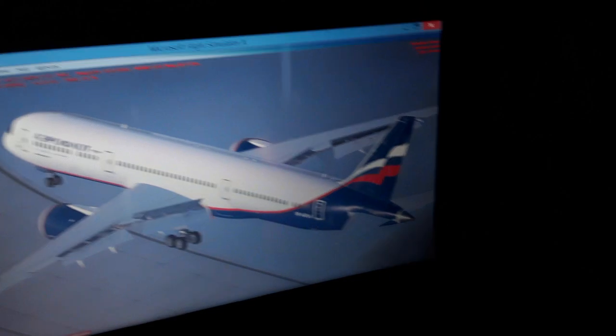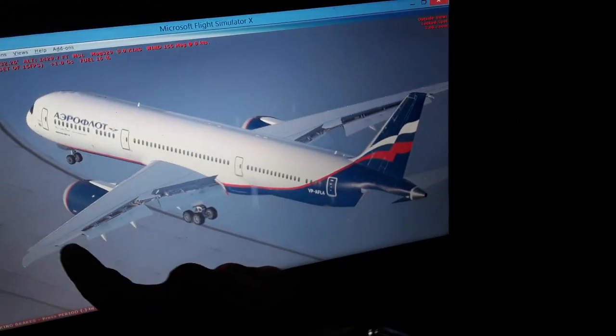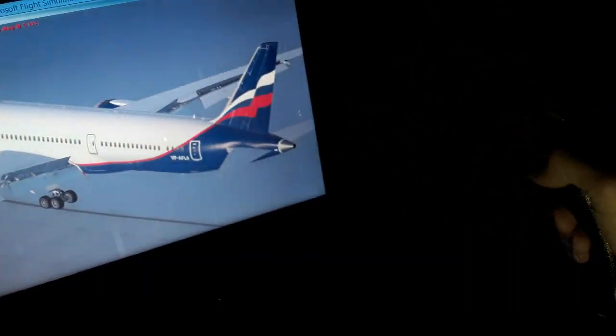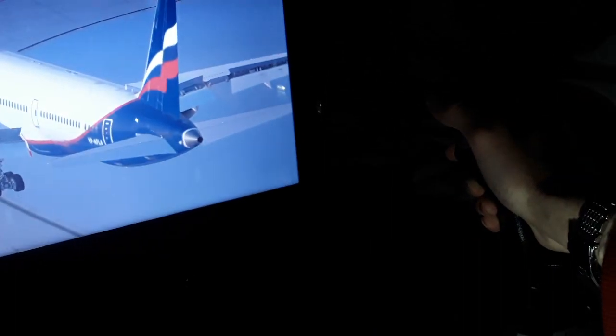We have also the wingtip. From wingtip, this axis is the pitch axis of the aircraft as it flies. So the pitch axis is for climb and descent. In the Airbus it is the side stick, up or down like this. You move the elevator, same like in the Boeing. You move the yoke to move the elevator up and down. So it's the same principle.